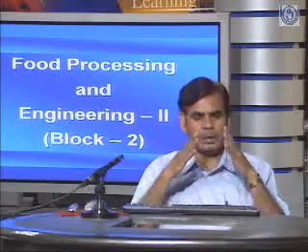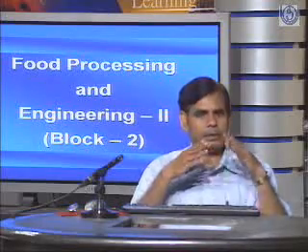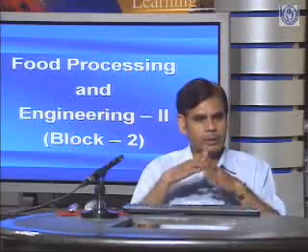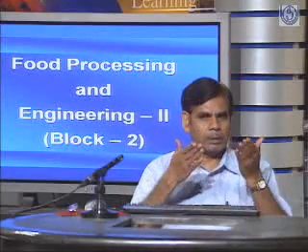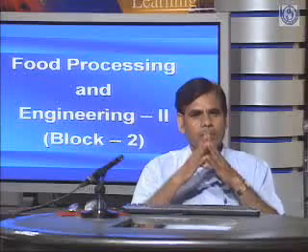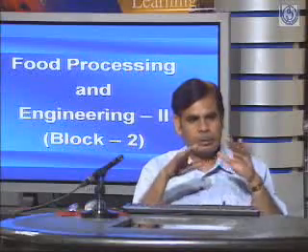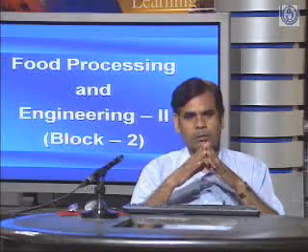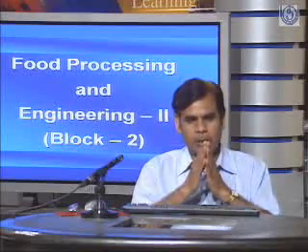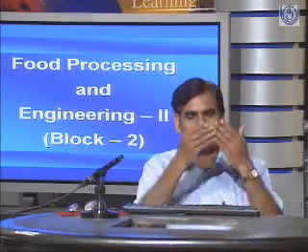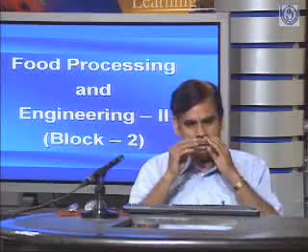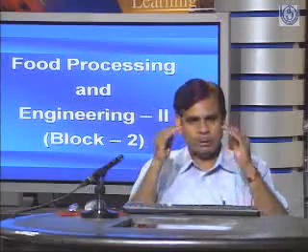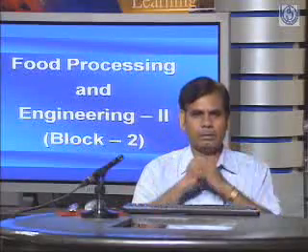In the same way, the water available in the center of the product has to travel from the center to the outside. The dried thick layer hinders both conditions, because the traveling distance from the center to the product surface is longer, so it will take more time.